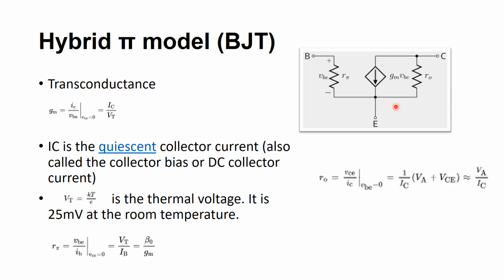Whenever you have a BJT and a circuit associated with the BJT, the first task of a designer is to draw its equivalent model just as shown in this figure. This helps the designer to analyze the circuit behavior, especially when deriving an AC response or frequency response of transistor circuits. So we see now your base and emitter is the input side and the voltage is vbe, and your collector and emitter is the output side.